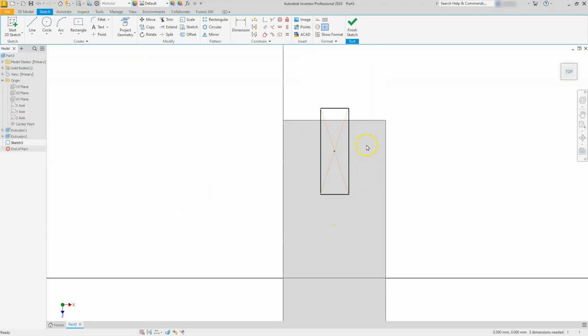Okay? I'm going to give it a dimension so this line will project in now. So if I go to dimension, this back line to this front face here, and make it 50, you can see that yellow line will appear. And now I could have been able, or would have been able to use that vertical constraint on that midpoint. But either way works fine.